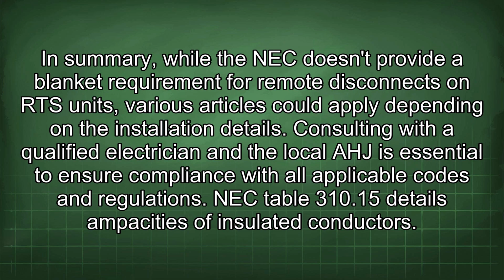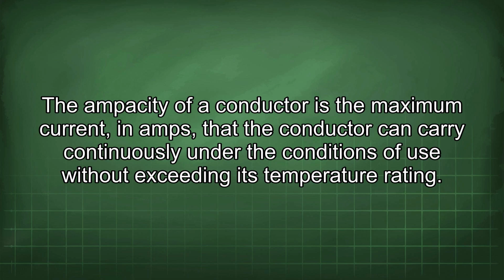NEC Table 310.15 details ampacities of insulated conductors. The ampacity of a conductor is the maximum current in amps that the conductor can carry continuously under the conditions of use without exceeding its temperature rating.